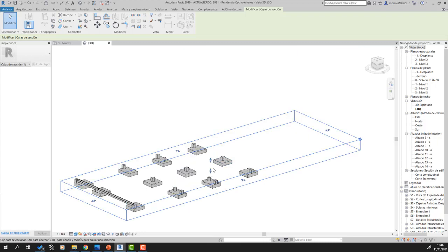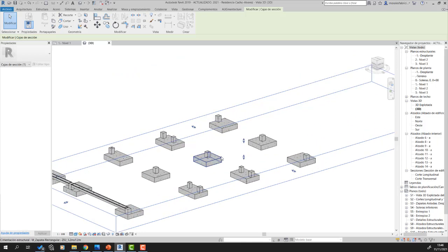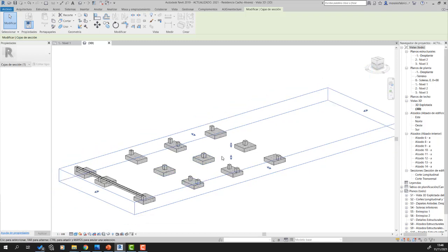start by the footing. The footing system is responsible for transmitting the loads to the ground, and specifically for this house the footing system consists of isolated footings. These pads are made out of reinforced concrete, and the loads that come from each column go directly to the concrete pad, and the concrete pad, which is called the footing, transfers the loads to the surrounding soil.